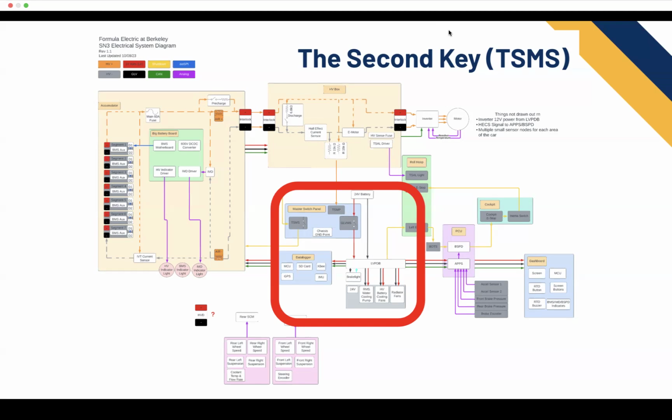All boards with high voltage, just a note, are also sprayed with conformal coating, which puts a thin layer of, I don't know exactly what the chemical or material is, non-conductive film over everything so that nothing would short, and it also stops corrosion and such. But yeah, it's placed in there because it makes harnessing easier, and also there's high voltage, so it has to be contained.